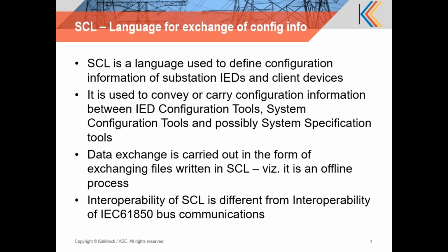So data exchange in this process is carried out in the form of exchanging files written in SCL. That is, it's basically an offline process. It's not like a client-server request-response kind of process. And finally, the interoperability of SCL when it goes between these tools is a totally different thing as compared to the interoperability of the 61850 bus communications that go between the IEDs and the clients.